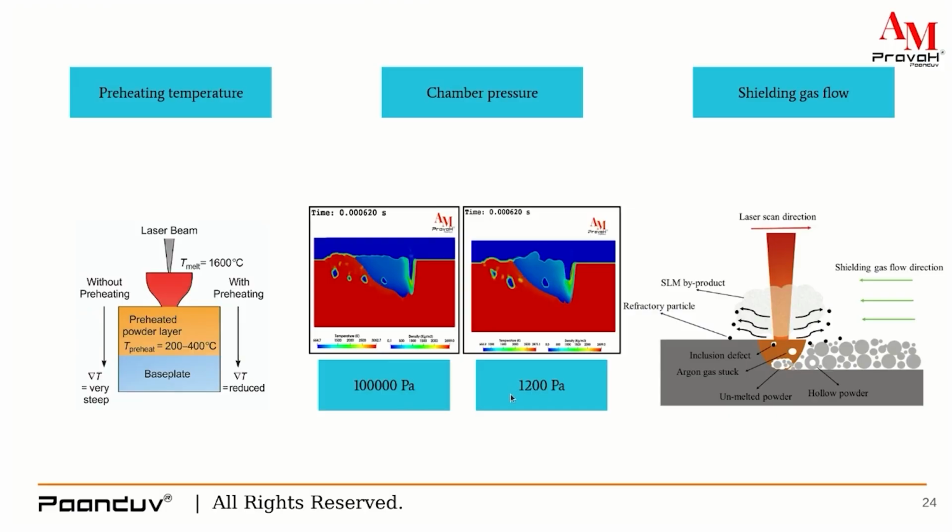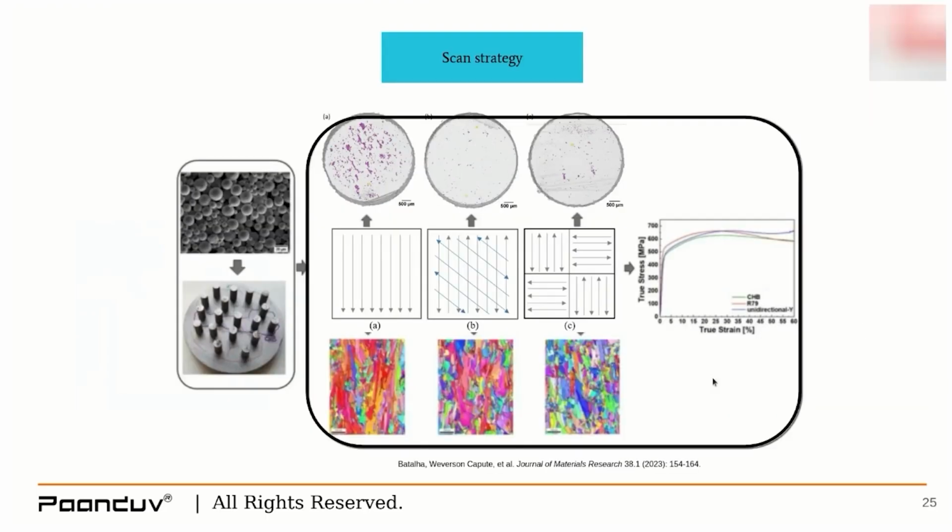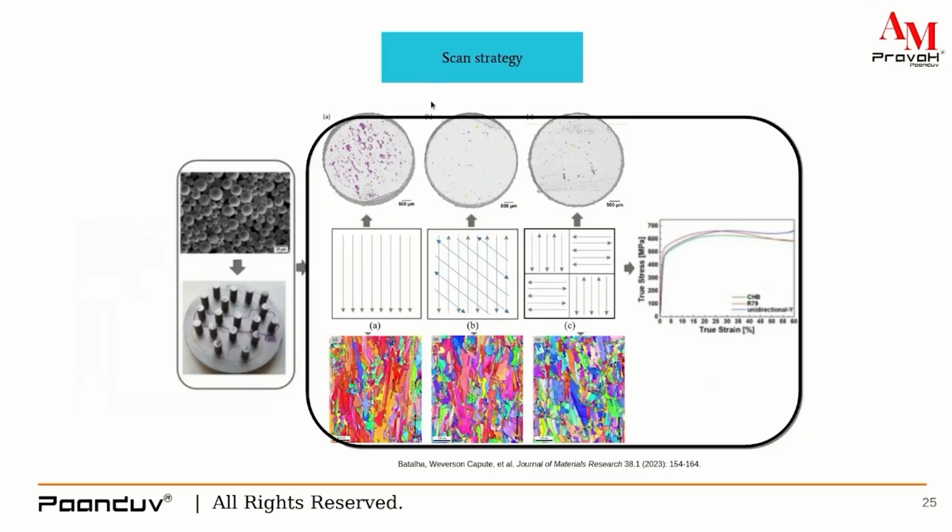The first example is an aluminum based alloy. This is a steady state. This is a conduction mode melting and solidification that you see on screen. As the laser progresses, you can see a yellow spot which shows the higher temperature in that region, and the surrounding liquid is red, which shows that the temperature of the molten liquid is relatively lower in those regions. We have also used the ray tracing methodology to have a better visualization with the post